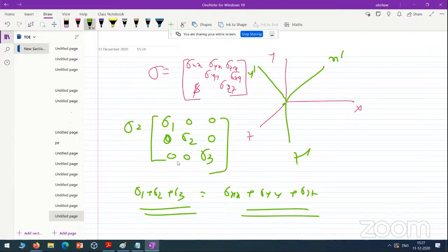I suggest you read different yield criteria and failure criteria, and look at how those criteria are represented through different invariants for different materials. For some materials the second invariant is more important, for some the first invariant is also important. It depends on what kind of failure it is. Sometimes they represent the failure in terms of load angle, which can be related to the third invariant. So it also depends on which kind of material, how you represent those criteria.